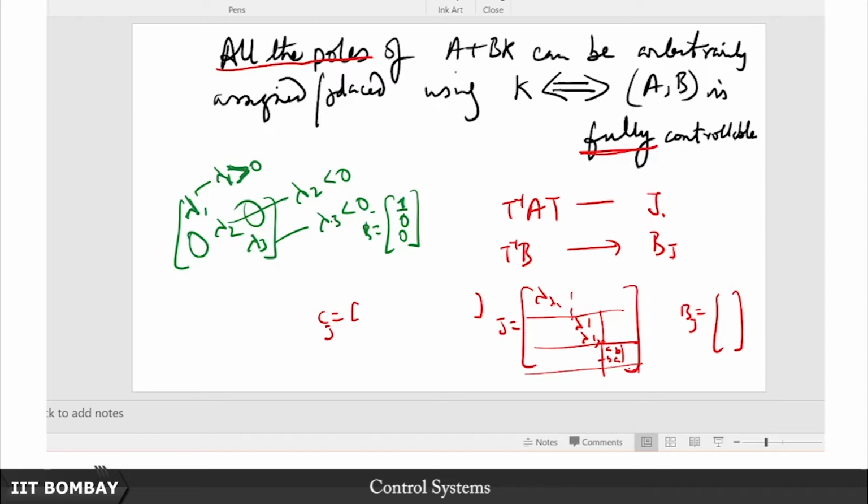So my inability to maneuver certain states does not result in instability. Even though I do not have full controllability, at least the uncontrollable states are stable, so that even if performance metrics may not be met, at least stabilization may be met. Those systems are called stabilizable. If it is not fully controllable, the next best thing we look for is stabilizability.